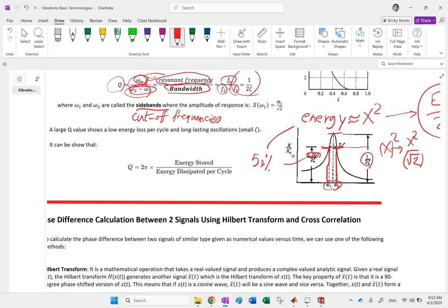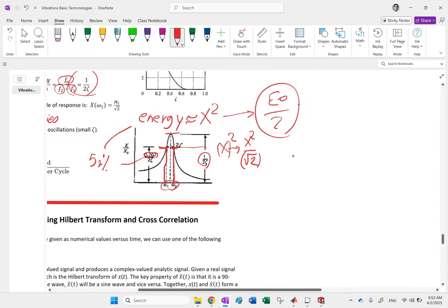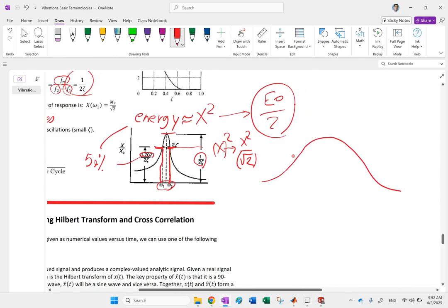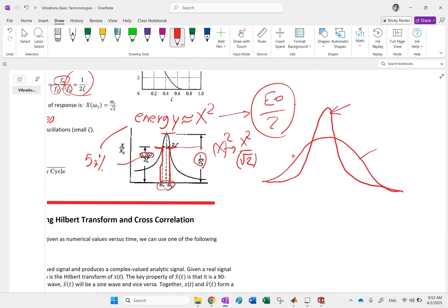And what does that mean? Well, one resonance can look like this, and one resonance can look like this. So this one has a sharper resonance than this one. What does it mean? It means your values increase much more drastically when you get to resonance than this one does. And this one is, of course, more dangerous, because the response of the system increases very fast as you increase the excitation frequency closer to the natural frequency. This one takes a more gentle approach, so it is not as dangerous as this one is.